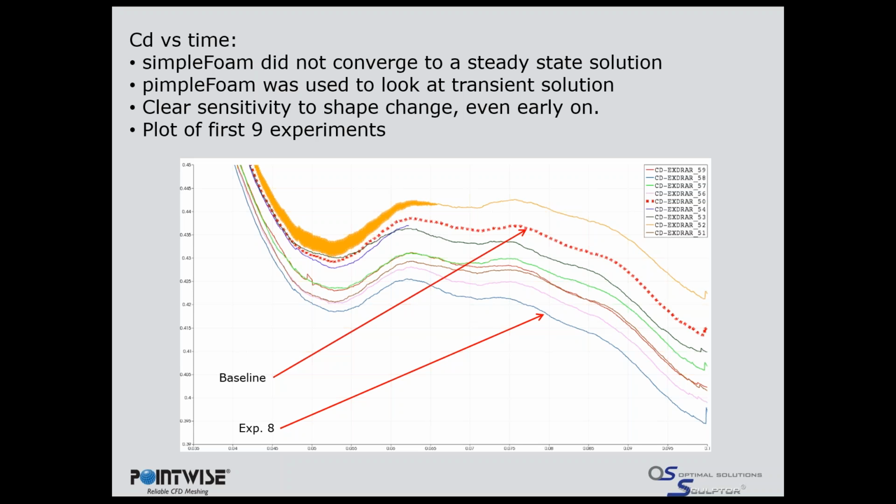But we see clearly that even early on in the solution, and by the way, to get a better solution than just using simpleFoam, we went to pimpleFoam, or the transient solution.